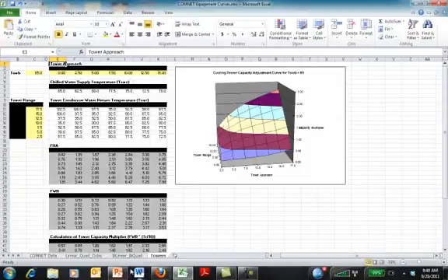Dick Lord from Carrier has been doing some significant work for the 90.1 committee to improve these curves, and when his data is available to us, we will take a look at it and probably dump the DOE2 defaults and use his, because he's developed data that better represents the minimum equipment that's specified in 90.1 and in NACA. His curves right now, I believe, deal mostly with chillers, but they're going to be expanded to include direct expansion equipment as well.